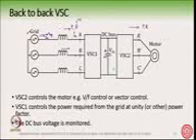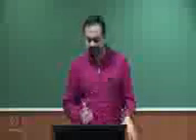Once you do that, the VSC will take power at unity power factor from the grid. This is usually the case. We always want the current drawn from the grid to be at unity power factor, so that the grid does not have to support any reactive power. So we make sure that the VSC phasor is such that VAG and IA are in phase.